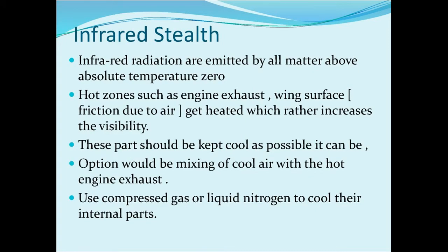Infrared stealth. Infrared radiation is emitted by all matter above absolute zero temperature. Hot zones, such as the engine exhaust and wing surfaces heated by air friction, increase the visibility. These parts should be kept as cool as possible. One option would be mixing cool air with the hot engine exhaust. Compressed gas or liquid nitrogen can also be used to cool internal parts.